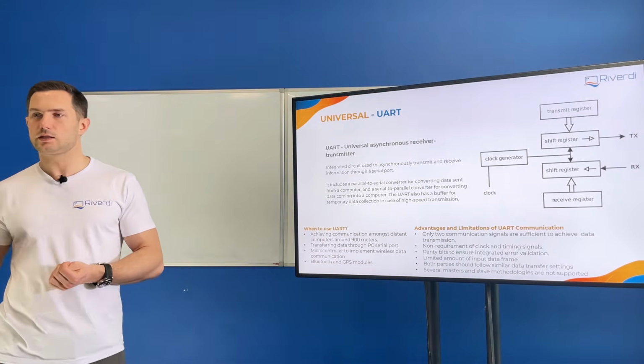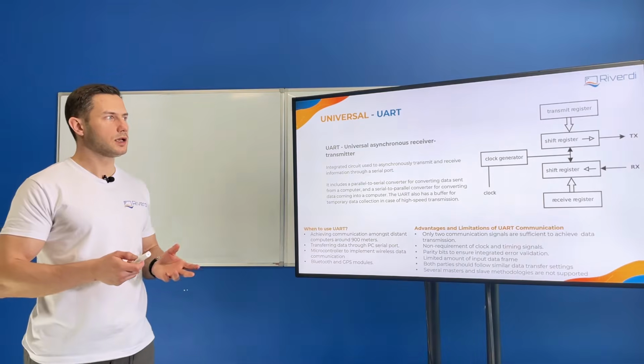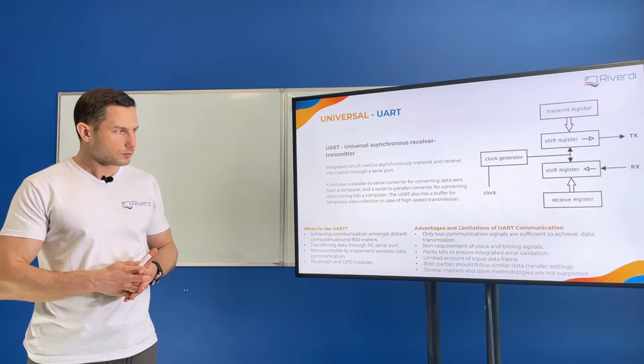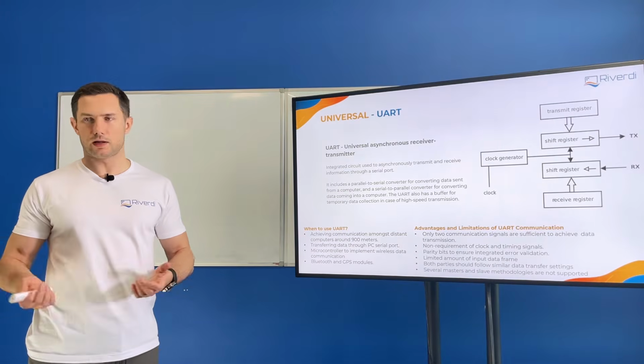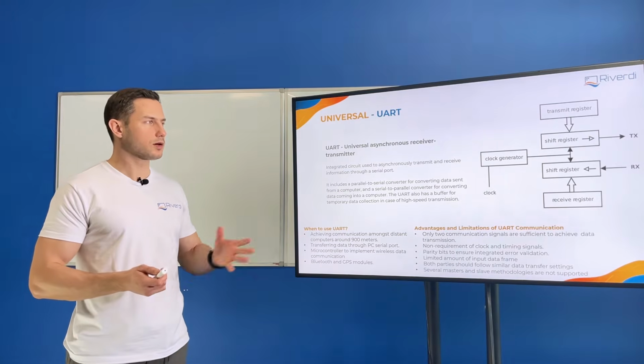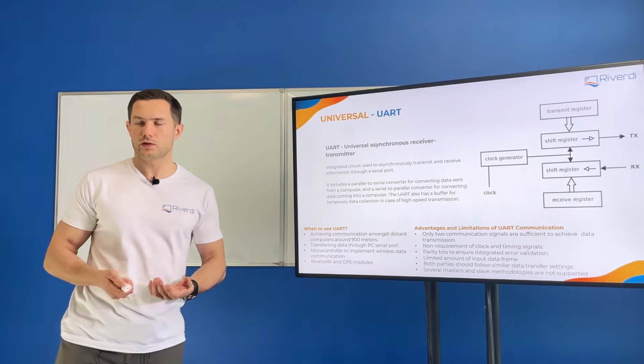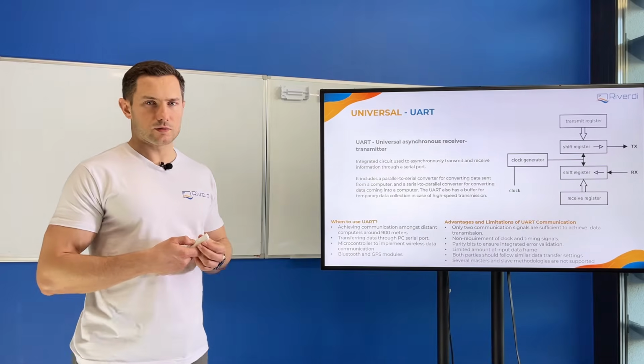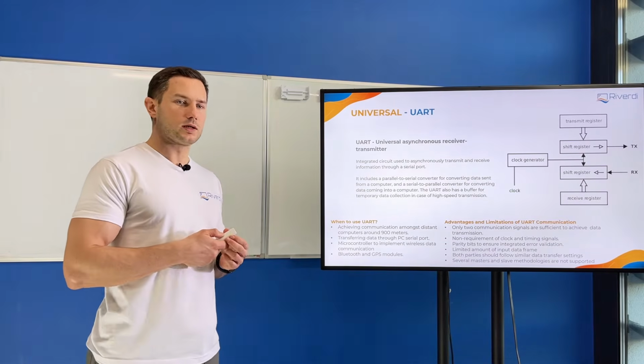That is not the case in SPI or I2C, because we have a clock there, and the clock gives the speed to everyone. Yes, so everyone works according to the clock. In UART we don't have a clock, so first we need to agree what speed we will use. UART is rather not used for the image transfer, or it's very slow.